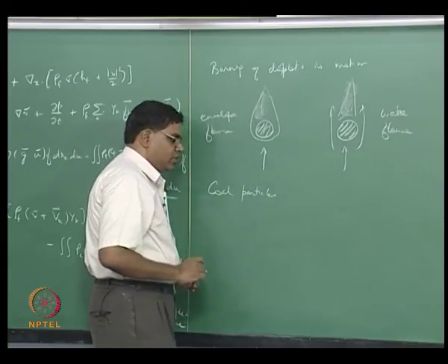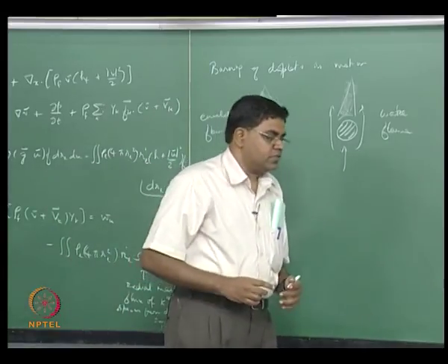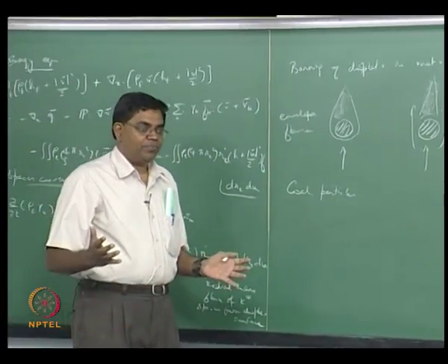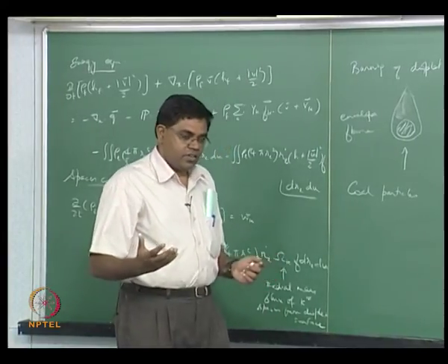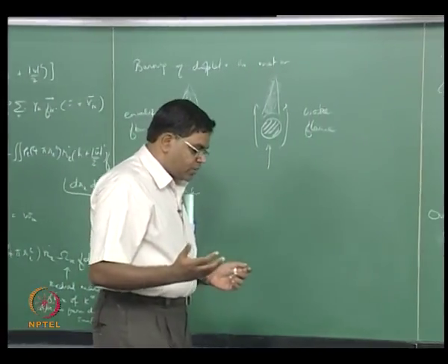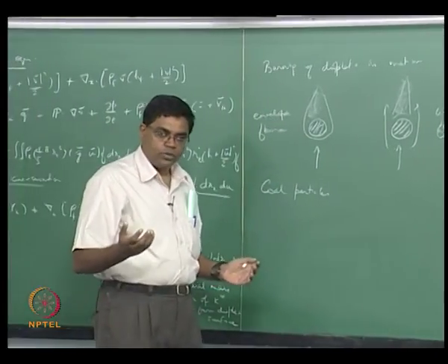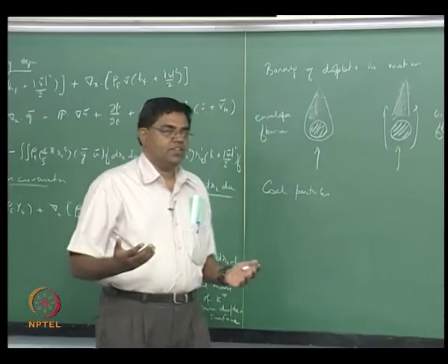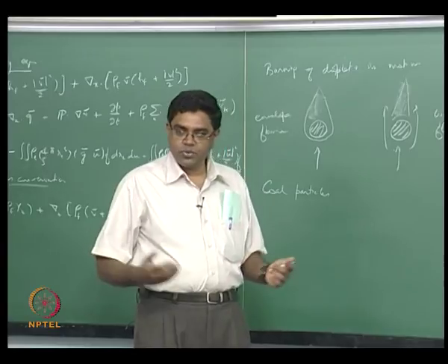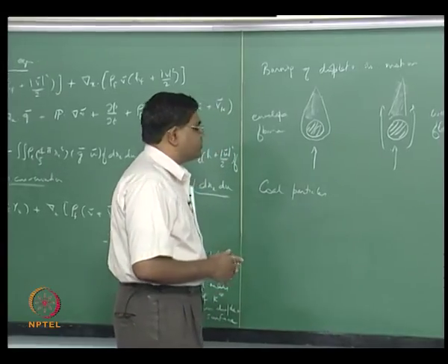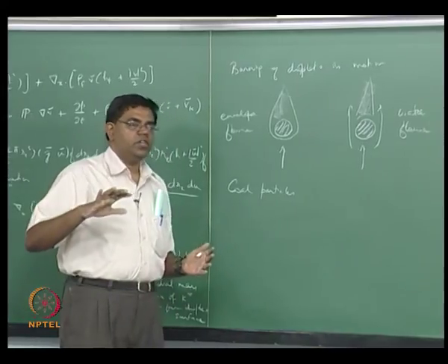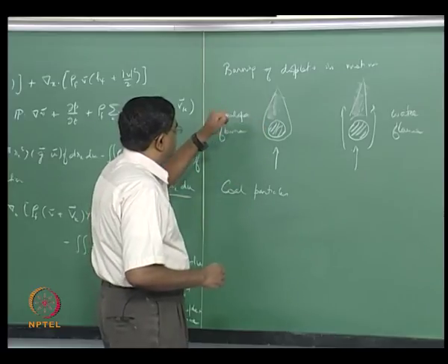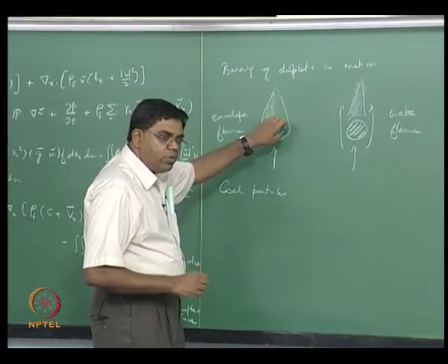penetrating through that and then coming out as gas, right. One of the dramatic examples for that is something called aluminized gelled kerosene. Kerosene itself is a multi-component fuel. On top of it, let's say you try to gel it with aluminium, and aluminium is obviously less volatile when compared to kerosene. So what happens in these kinds of situations, where you have a mixture of materials of different volatility, is that the less volatile substance will begin to accumulate on the surface as the surface is regressing, right.